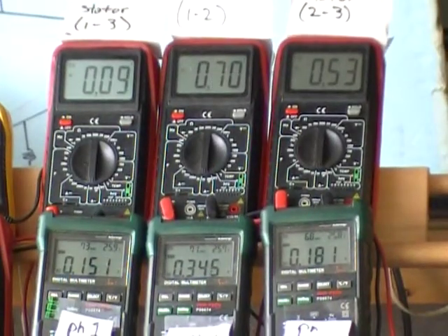Now we're going to go in there and turn the field on and look for any kind of ratio changes between the stator line currents, which were formerly noted to be excessive. 0.15, 0.34, yes, they're still excessive. Stator line 1, 2 has been formerly measured to have 34% excessive amperage versus the phases it serves, 1 and 2.